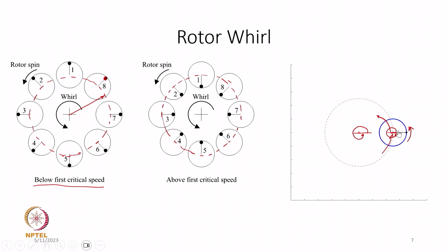That is what is typically called in practice of rotor vibration a synchronous whirl. Synchronous whirl meaning it is synchronous to the speed of rotation or spin motion. But again, let me remind you that it is this whirl amplitude that is vibration, and the spin motion is the rigid body rotation of the shaft about its own axis. All right. So, this is how it looks.